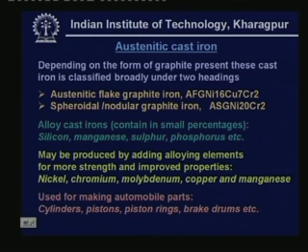All these things are very well designated by the letters given beside the name, meaning austenitic flake graphite iron. We consider one of the examples like AFG Ni16 Cu7 Cr2, where Ni is nickel, Cu is copper, and Cr is chromium. So, AFG you understand, austenitic flake graphite, then Ni is nickel, copper and chromium.